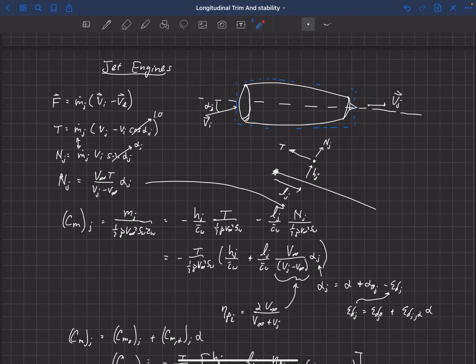There are many indirect effects actually that come from a jet engine, because this slipstream that's coming out down here can affect lifting surfaces behind it, and it can even entrain flow around it. And so if you have lifting surfaces even above or nearby this jet engine, they can see higher velocities simply because of flow entrainment. So these types of things, the slipstream behind or the entrainment, those are what we call indirect effects.